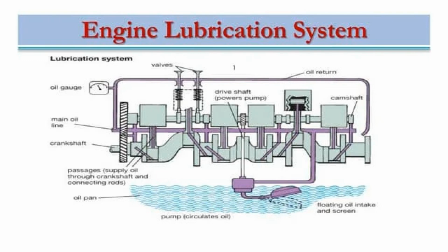It does not provide uniform lubrication because oil condenses on the lubricated surfaces randomly. It requires a much larger quantity of lubricant because the lubrication process is quantized. The probability of oxidation of metal surfaces increases. In most cases, cars use a combined scheme of oil circulation in the system, which is characterized by the disadvantages and advantages of both of the above methods.